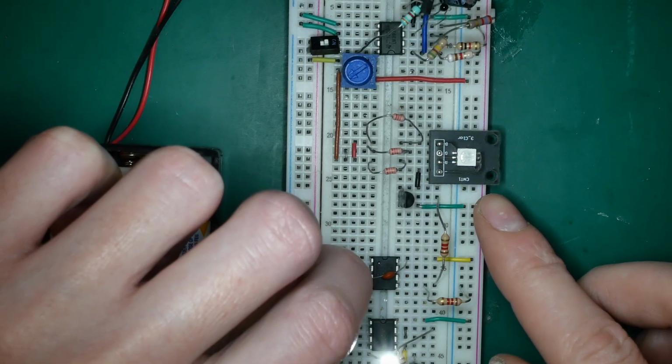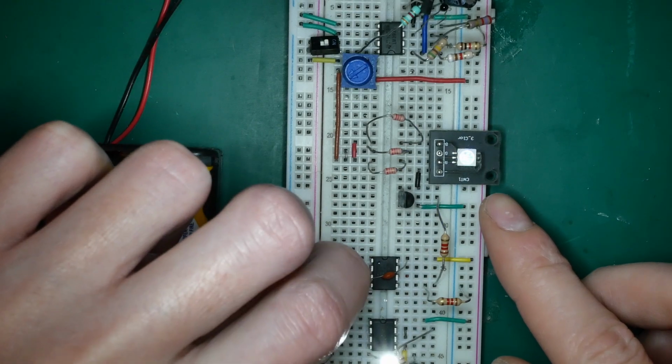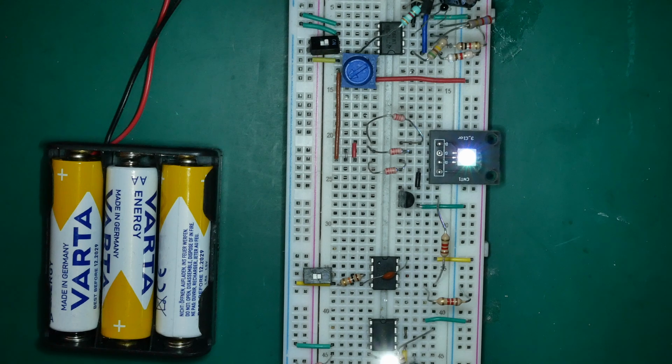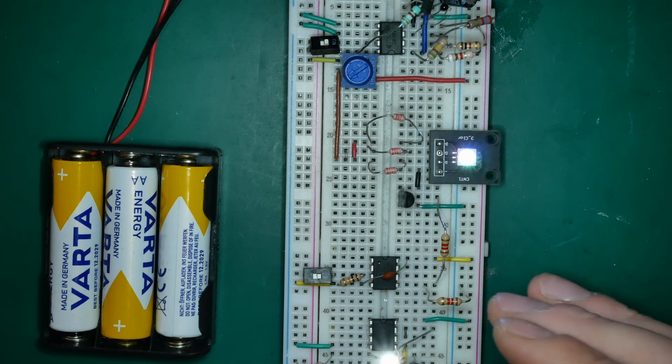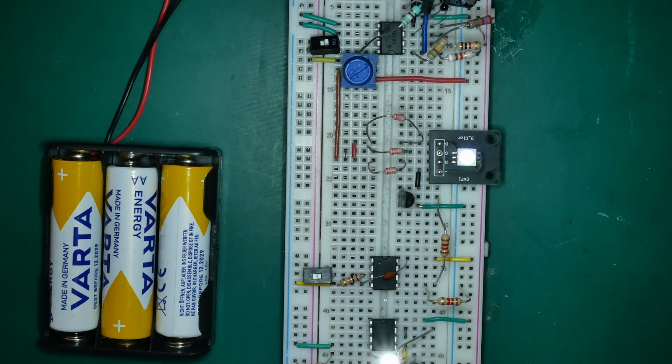I'm not quite sure. To fix this, I switched to phase correct PWM, which handles the transition around zero most symmetrically and avoids the glitch. As you can see, the switching is not immediate, and that's intentional. I designed it this way to keep the behavior simple and smooth.